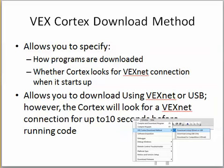All right, here we go. VEX Cortex download method. It allows you to specify how programs are downloaded, whether the Cortex looks for a VEXNet connection when it starts up, allowing you to download using VEXNet or USB. However, the Cortex will look for a VEXNet connection for up to 10 seconds before running code.